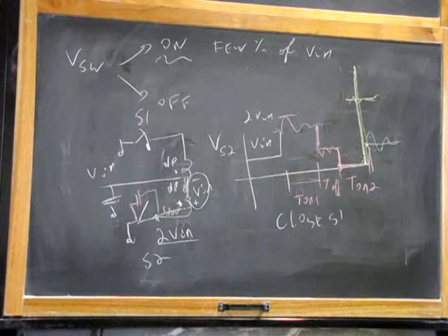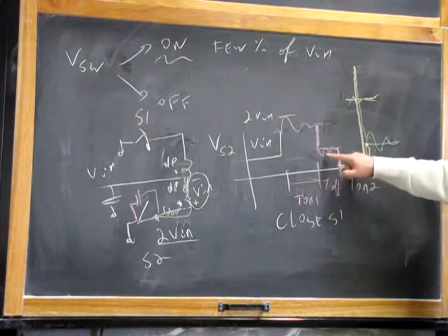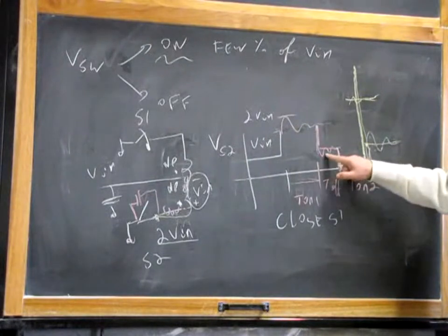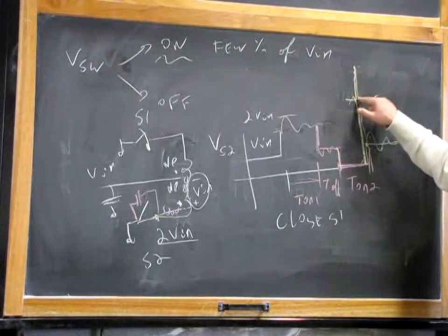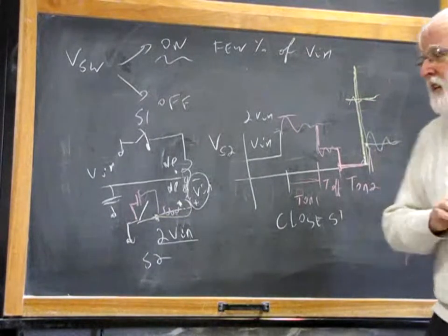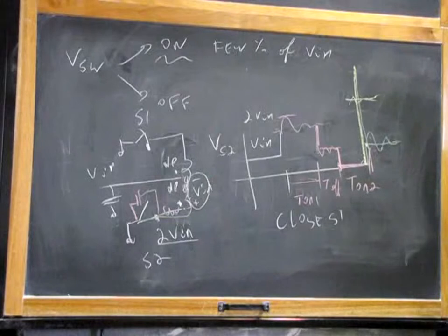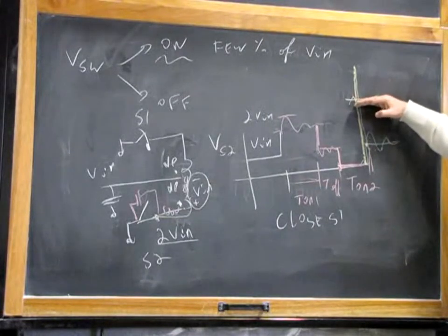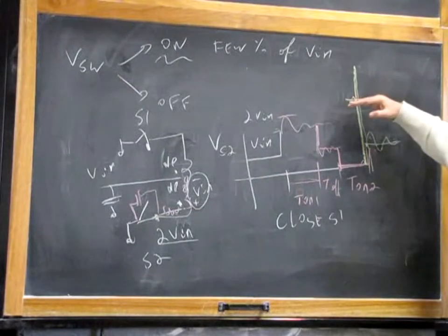Or you can use specific snubbers, not RC snubbers as we are used to design. To stand these oscillations, you can use an RC snubber as we learned in the past. But for this peak, you cannot; you use a snubber that has a different topology, a different circuit. I don't have time to explain this. Or you can use a transil over here, Zener diode, but you have to plan this. Otherwise you risk kaboom.